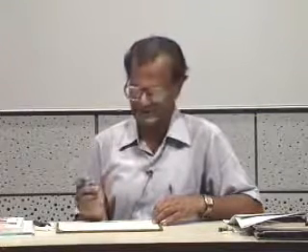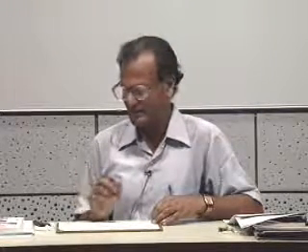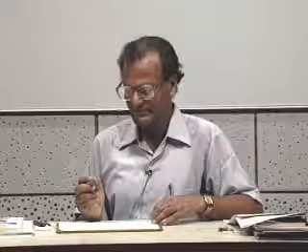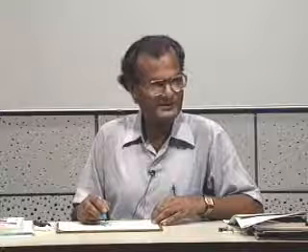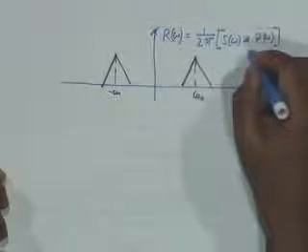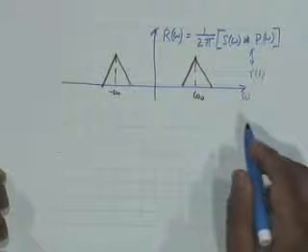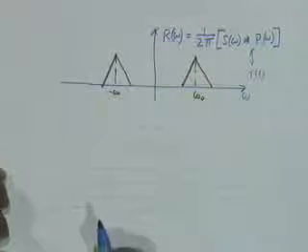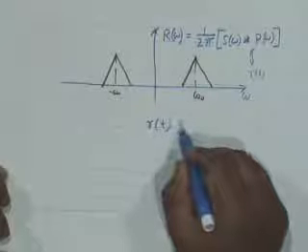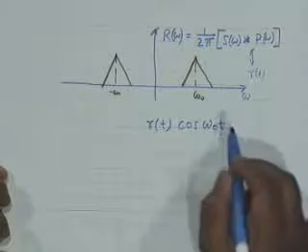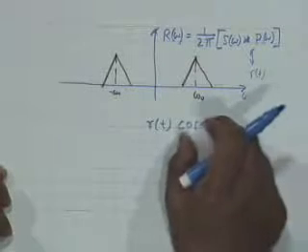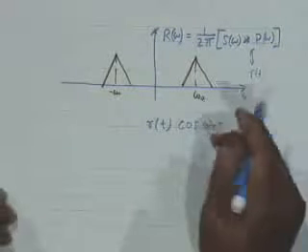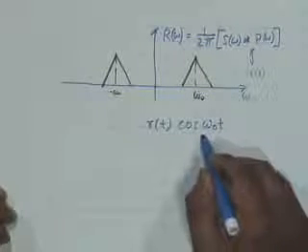A very simple method, there are many methods which you learn in the principles of communication engineering in the third year. Now, a very simple method would be that whatever you get here, suppose this is R of t, this is the signal that you receive in a receiving antenna. Then what you do is you multiply R of t by, again, the same high frequency called the carrier, because omega 0 carries on it the low frequency spectrum. So this is called the carrier.